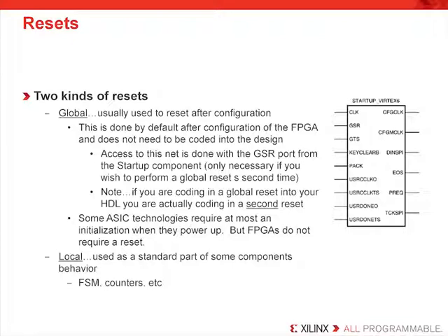Now, to learn more about that, check out the Xilinx Unified Libraries Guide for more information. This GSR will give you access to the ability to activate a global reset whenever you desire. But note, this routing is slow, and its timing is uncharacterized. It is not recommended that you use it unless you're prepared for poor global reset timing.